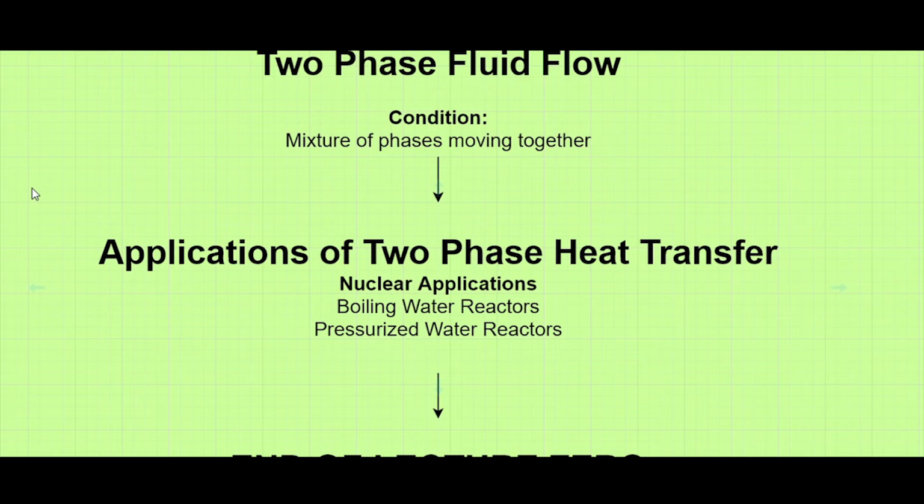Similarly, in pressurized water reactors, we sometimes want localized boiling due to heavy loads, or even bulk boiling in the case of emergencies and some transient conditions. We have to know the exact mechanisms of how these processes are going to take place, and what will be the temperatures and the heat transfer coefficients all over the reactor, how many bubbles are going to be formed, how is it going to affect different system parameters like the moderation. We study two-phase flow because a phase change process helps us remove or add a vast amount of heat, much more than the single phase flow. So this is something we want to utilize and hence have to learn.